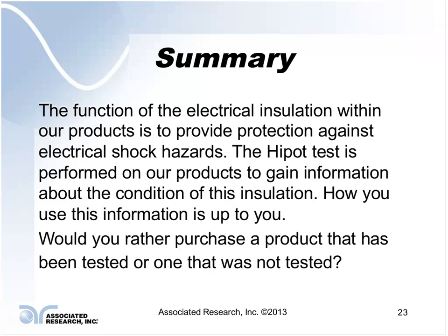When you define a Hipot failure, it's essentially where the current flowing through the circuit under test rapidly increases in an uncontrollable manner, to the point where it trips off the current trip setting of the Hipot tester itself.